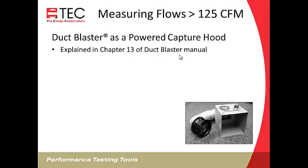So it's back to the same pressure as it was before you created that restriction. So in this photo, we're showing the duct blaster set up for pressurization. You see this is the side with the flow sensor on, the side with the rings on, and for measuring exhaust fan flow, we're going to need to turn that fan around.